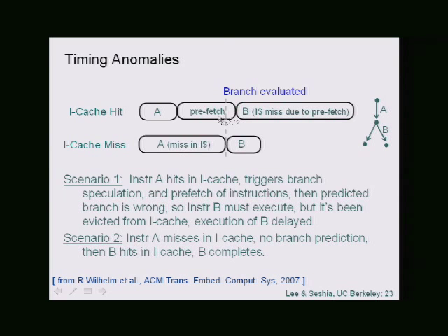on an embedded processor, where they thought, oh, to get the worst case time of A and B, I'll just take the sum of the worst case of A and the worst case of B, and that will be the biggest value. But they didn't account for the fact that you can have speculative execution going on in the processor, which can incur a penalty, and you have to also add the small number of cycles that corresponds to dealing with that misprediction. Okay, so